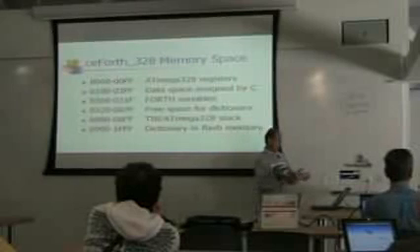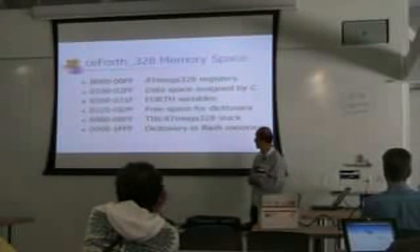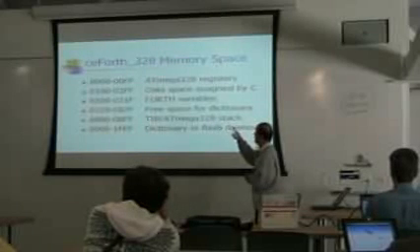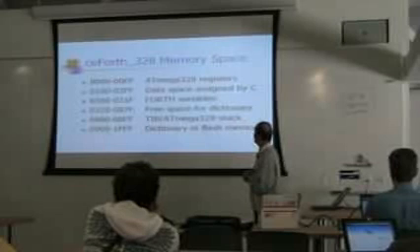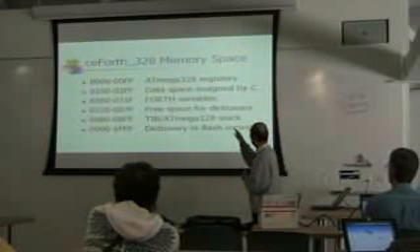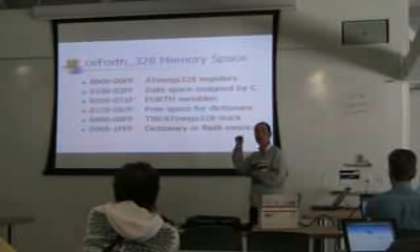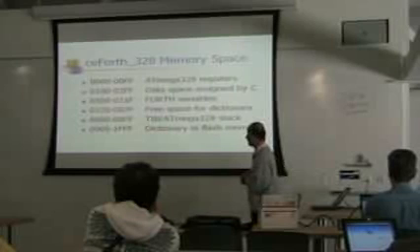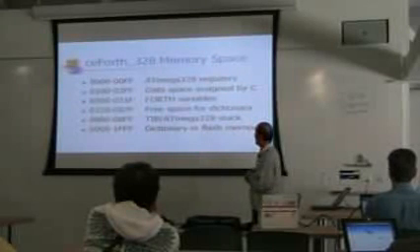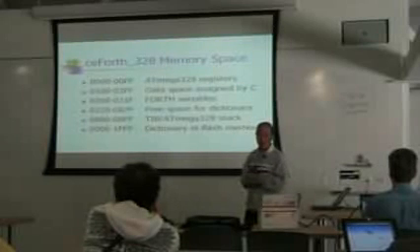In this unified memory model, the space from 0 to FF is the ATmega328 registers. The first 32 bytes are actually mapped into the ATmega328 CPU registers, and then the next ones up to FF are I/O registers.